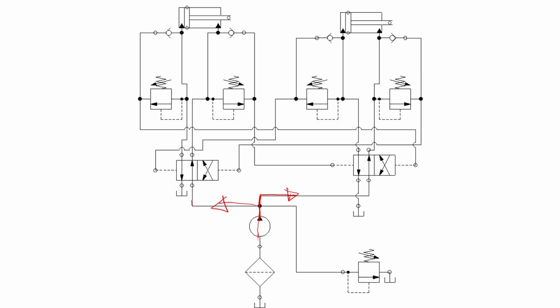First, we're going to follow the left line, and this passes through this directional valve, goes all the way to the rod inside, and then because this cylinder is fully retracted, it cannot go anywhere. So nothing will happen on this side. So flow will try to go in this way. However, this check valve only allows flow to the left, but not to the right.